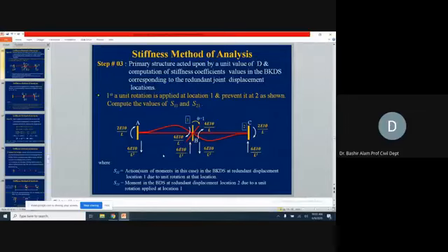If we give rotation, these are the actions generated. Now for the left hand side, let's balance this one independently, because this was a fixed support. The clockwise direction has to be balanced by a counterclockwise couple. So this is how we fix the directions of these reactions: this will be downward, this will be upward. How do we find out its magnitude? It will be simply the summation of these moments. So we have 4EI plus 2EI, which is 6EI theta divided by L.